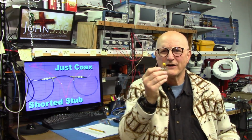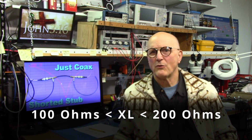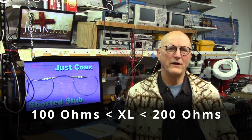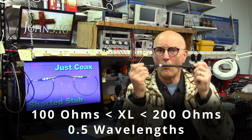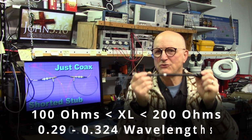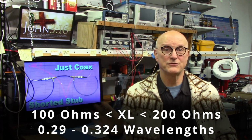Your coax, including the effects of the inductor, needs to be a half wavelength long. Adding the inductor to the end of your coax can only make up a bit less than 1/4 wavelength. And in practical terms, this is right around 0.248 wavelengths. Inductance is a pretty tough thing to deal with because every wire is an inductor and their values change with environment. From my bench experiments, it seems we would want to shoot for an inductive reactance around 100 to 200 ohms at the frequency in question. This will shorten the stub from a full 1/2 wavelength down to between 0.29 and 0.324 wavelengths and provides reasonable adjustability in whatever inductor you choose to use.